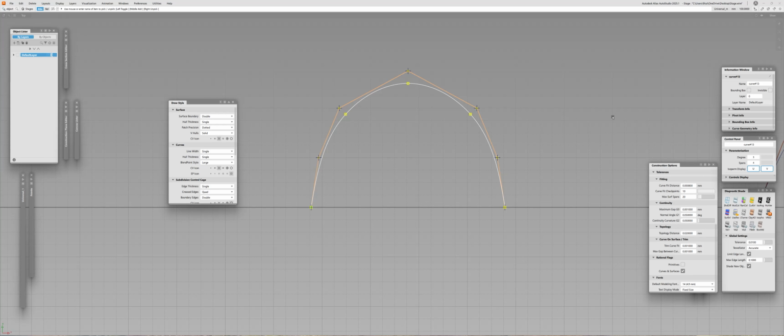So visually it's not uniform, but in the parametric space it is. That means that if we create a surface from this and divide it by isoparms, they will be very uniform, because the surface is constructed in a way that forms the inner parametric structure of UV coordinates.